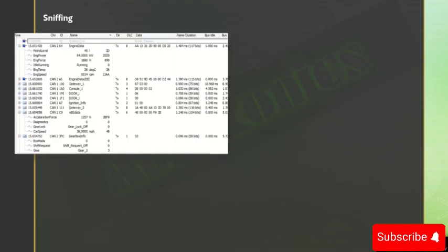Let's talk more about sniffing now. What is sniffing? Say for example, you have a vehicle log, which in this case is CAN logs. If you connect with a CAN OBD and then see the traces, they will appear. Obviously, this has the DBC. For us, we have a local DBC, but in your vehicle, if you do not have a DBC, the CAN traces will be in raw hexadecimal format where you cannot see this engine data, gateway, door or console messages. But here, since I have a DBC, it shows the proper value of the message along with the description, properly structured.